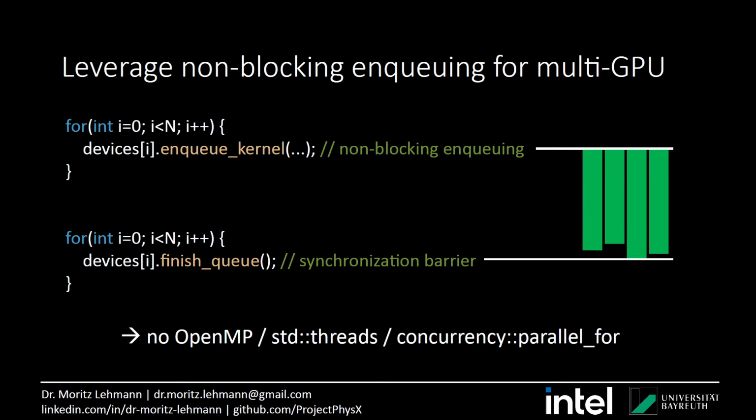They're the so-called boundary models, and friction slip is one way to do it. The boundary layer itself acts a bit like a lubrication layer for the air above the rest of the wing, and if you would directly resolve the turbulent boundary layer, you would need microscopic grid cells, and it totally blows up the memory footprint. So it's difficult to do.